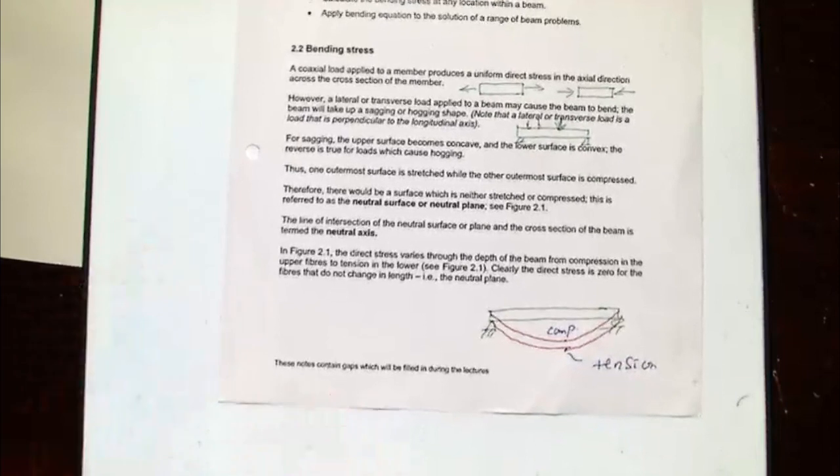What that means, therefore, is that as we go from one side to the other, you're going from tension to compression, or from compression to tension. The implication is that there will be somewhere in the middle which is not loaded at all, because in order to go from tension to compression, you have to go through the point of zero. So it means you have a point where there's no load. What we'll be showing now in our derivation is the magnitude of stress if we know the value of the bending moment: what is the magnitude of stress that we will have at any point along the length, at any point through the actual cross-section of the beam.